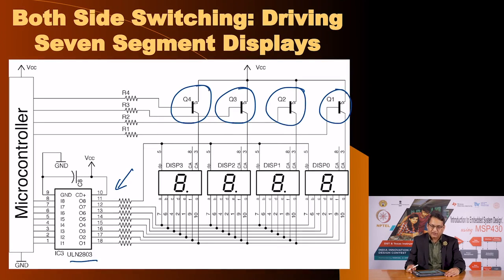In the next lecture, I will go through how this circuit operates, what are the limitations, how to calculate the values of these current limiting resistors, how to calculate the values of these base resistors for the PNP transistors. And since we are using an integrated circuit for the low side switch, we do not really need a resistor to control these switches. They can be directly driven from the logic output of a microcontroller.